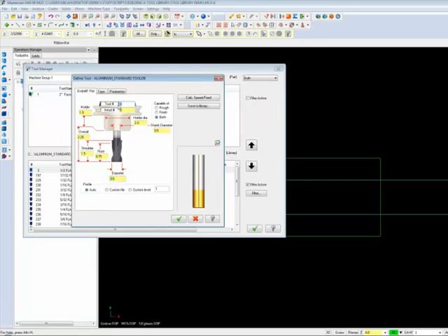It will be tool number 4, have an overall length of 3 1/4 inches, and a flute length of 2 inches. Notice that since the flute length is longer than the shoulder length, the preview window shows an X instead of the tool. Enter in a shoulder length of 2 inches.